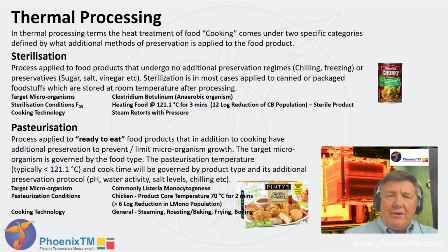For sterilization, we're targeting Clostridium botulinum, and we're looking to achieve a processing temperature of a minimum of 121.1 degrees for 3 minutes. And this is generally applied in technologies using steam retorts or pressurized cooking.